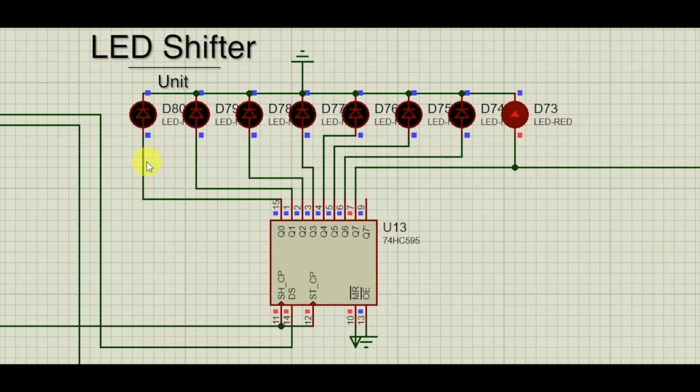This is the part of the circuit which controls the falling objects. For this circuit, we have used an 8-bit shift register with output latch. The output of each shift register is connected to a column of the 8x8 LED matrix. The output of the 3 to 8 decoder of the random number generator is set as input to the shift register. So, at any clock pulse, only one LED of each row will light up.